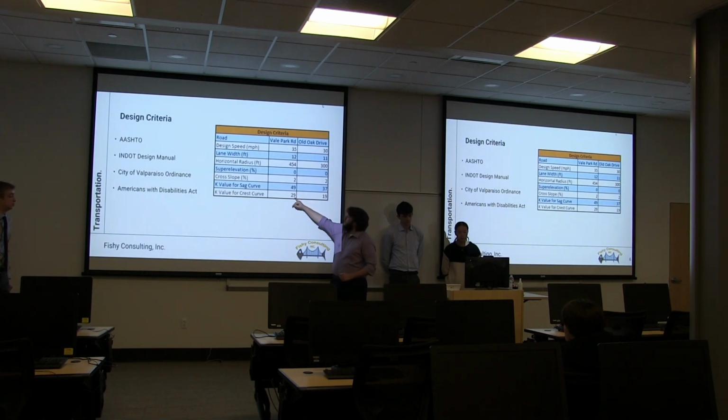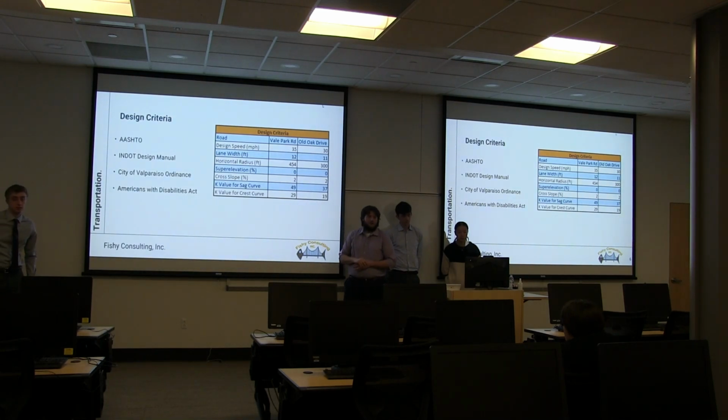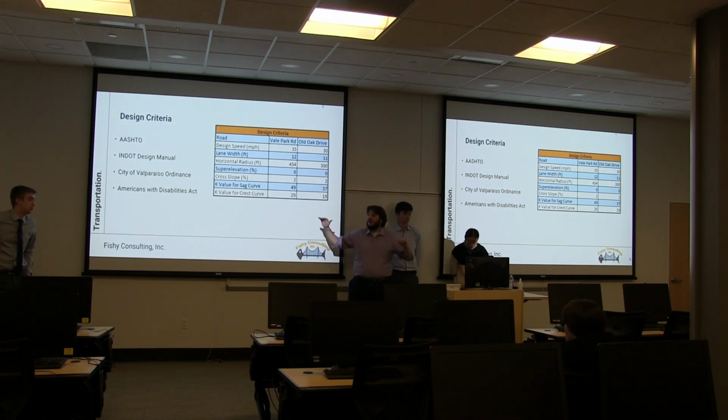I think my question is, how do you do it? In my old days, when we did this, I wanted to balance the cut and fill, so I did not want to be hauling any dirt out or bringing anything in. It was just connecting at the ends, starting at the elevations where the existing roads are, and keeping it as close to the existing grade as possible while staying within these values. So I just try to keep it on the existing line.